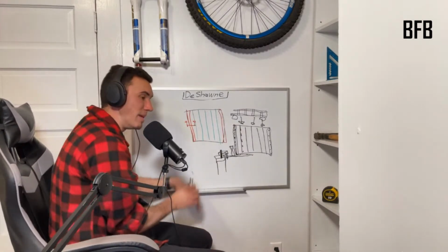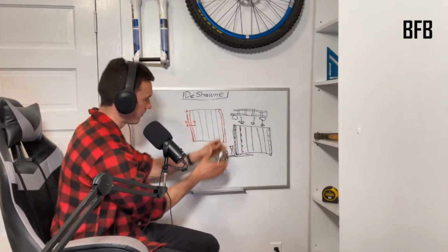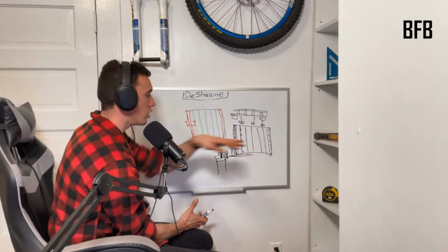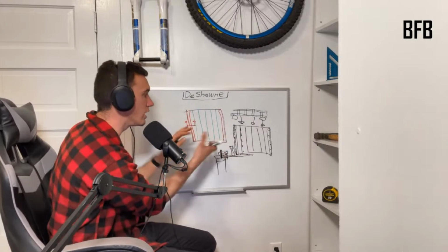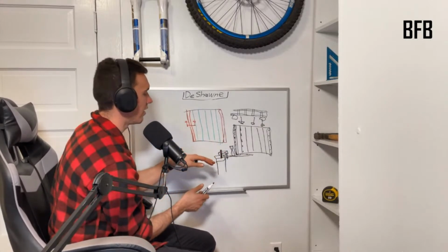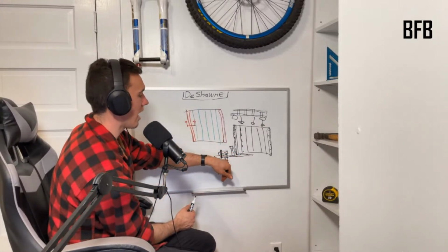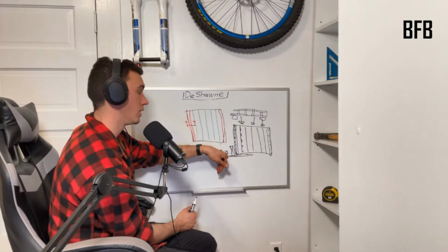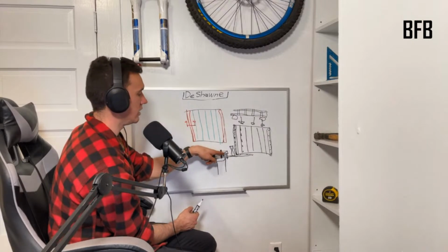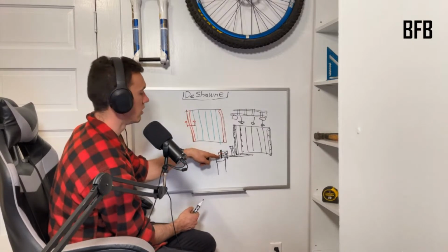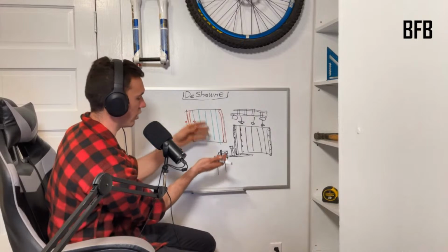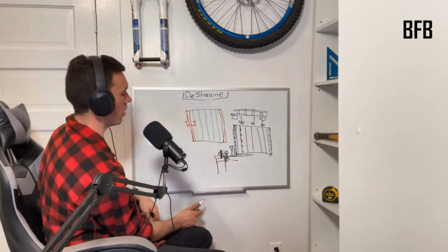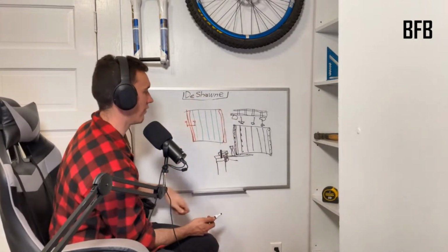And the diaphragm, being a system of components, is going to be sharing load between all of the sheetrock pieces and all the nails and all the wood connected. And that's why you stagger seams and stuff, right? It's going to share that load all the way out to the edge of the sheetrock, where that load will be transferred through the sheetrock screws and collected into these other pieces of wood, which will then transfer that load through the nails back into the top plates in the wall. And the top plates in the wall are the things that are resisting the diaphragm from moving.